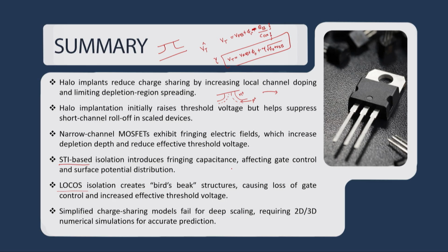We derived a basic equation considering the ideal case and without considering the bird's beak structure, such that we can relate how the charge shared by the gate over total charge is related with the depletion thickness and the width.